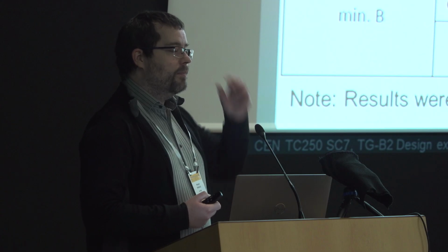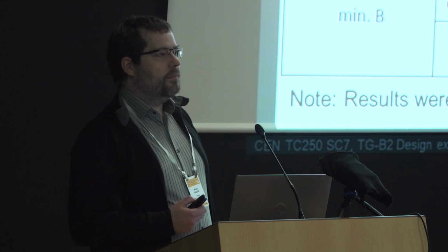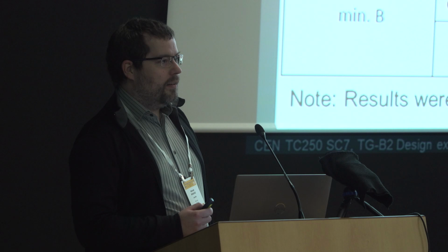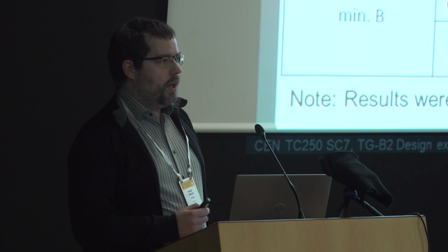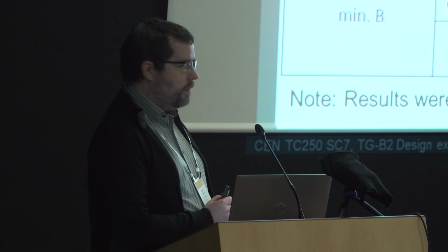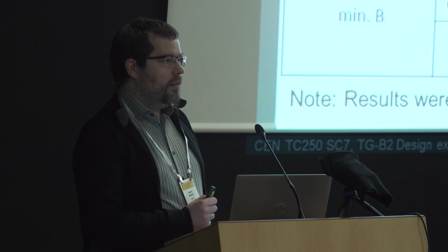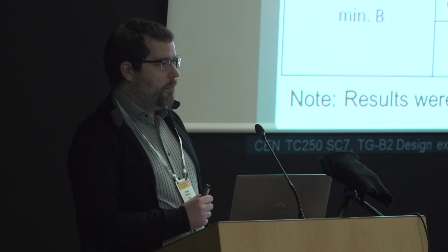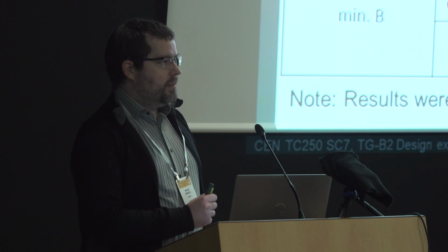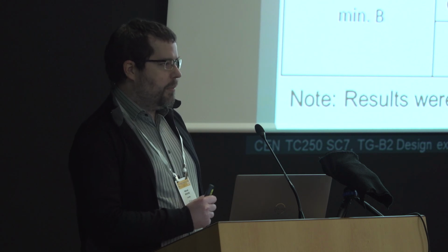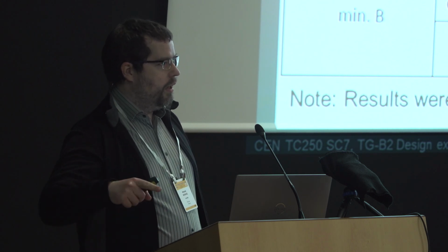Yeah. This question: where to put this, in fact KF or KM, is it optional? Can we put it wherever we want? No, we put it only on one of the things. Which one? Is that an option? Basically, if you factor material properties, it only makes sense to put it on the material factors.